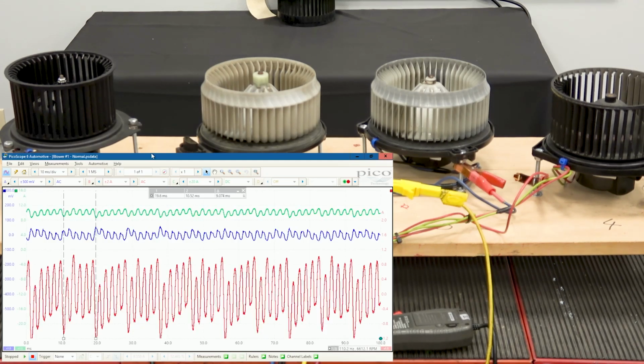I've opened it up static here, so I'm going to explain very quickly what we're looking at. The other thing I want to point out is, even if you don't have a current probe, if you have a simple, straightforward oscilloscope and you put it on the blower motor power supply, and you AC couple the scope, this way we will only look at the changing voltage component of the signal. On channel A, that's what we've got: volts, AC coupled, plus or minus half a volt, 500 millivolts.